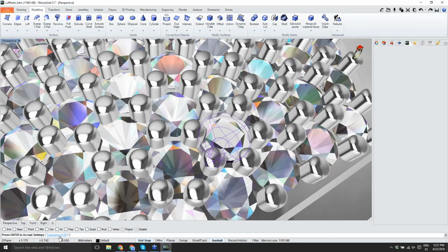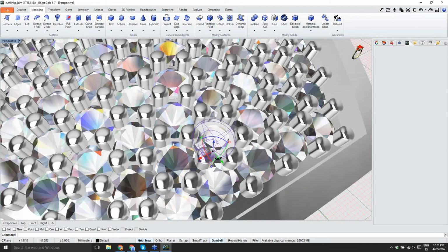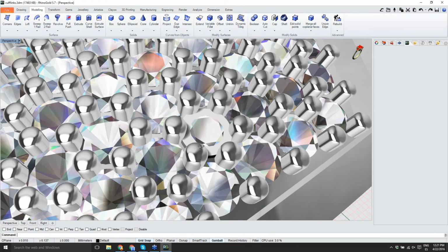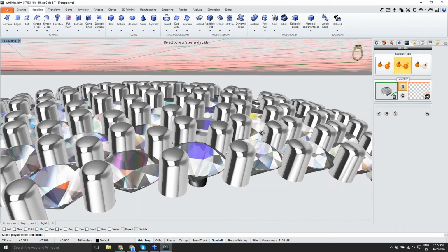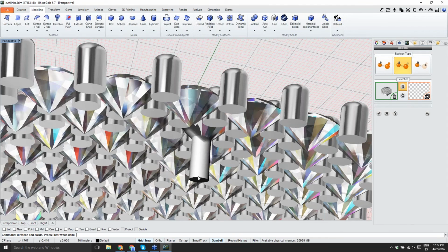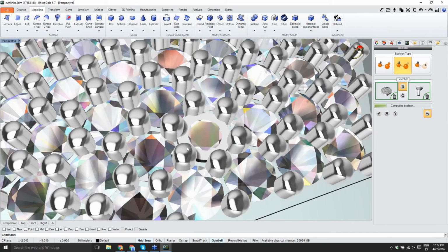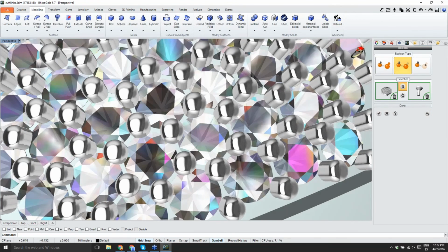In this case, as you can see, the tolerance in the command line is 0.05. So it will move it randomly to allow us to make the Boolean difference successfully. So I go back to the Boolean operation after the Shake Objects, and I select the cutter that was missing. And now once again I preview, and I click OK to apply the changes.